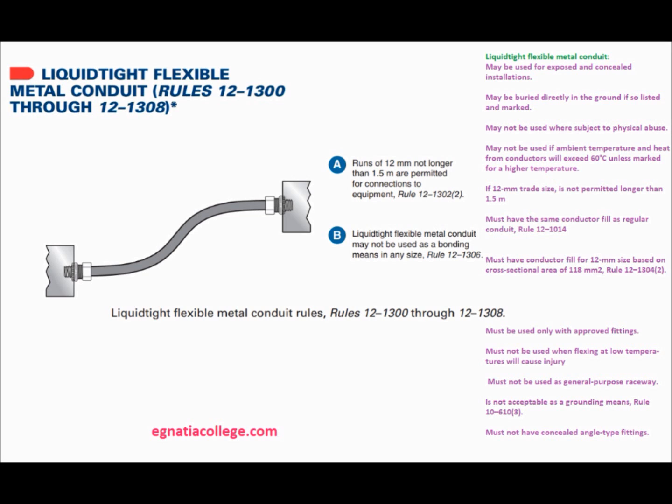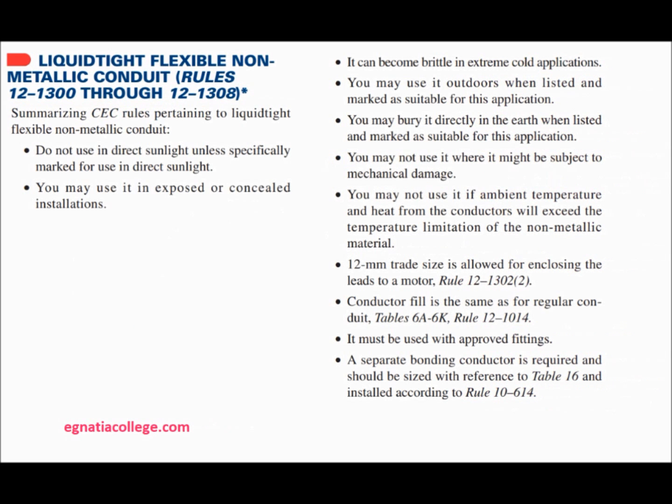Liquid-tight flexible non-metallic conduit. Summarizing CEC rules pertaining to liquid-tight flexible non-metallic conduit. Do not use in direct sunlight unless specifically marked for use in direct sunlight. You may use it in exposed or concealed installations. It can become brittle in extreme cold applications. You may use it outdoors when listed and marked as suitable for this application. You may bury it directly in the earth when listed and marked as suitable for this application.